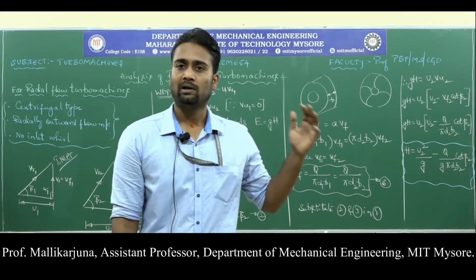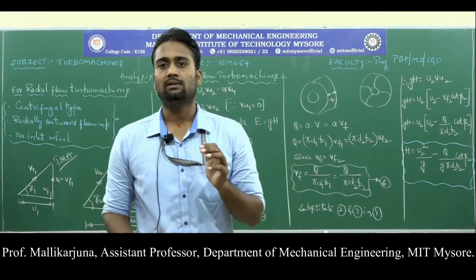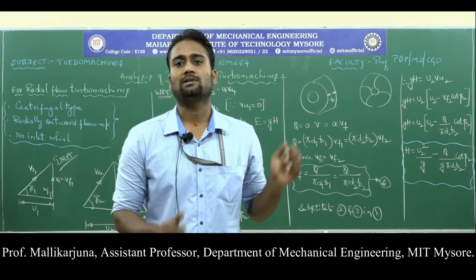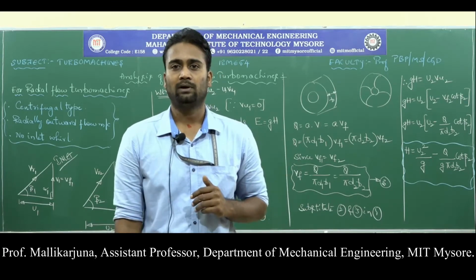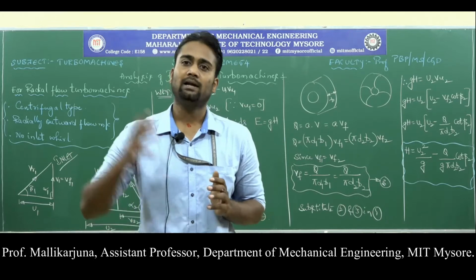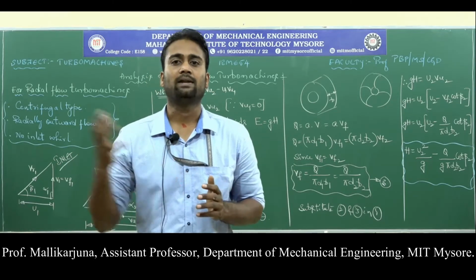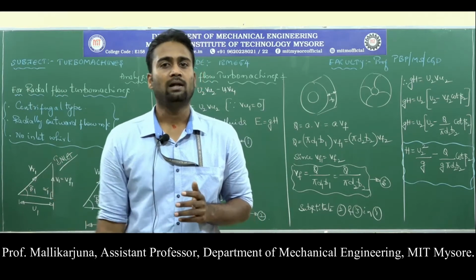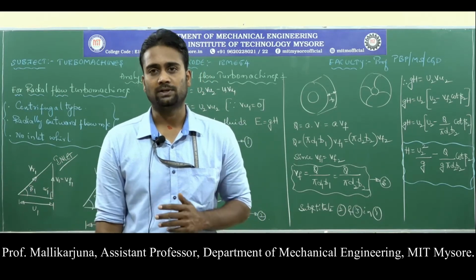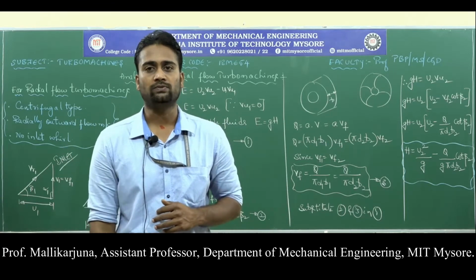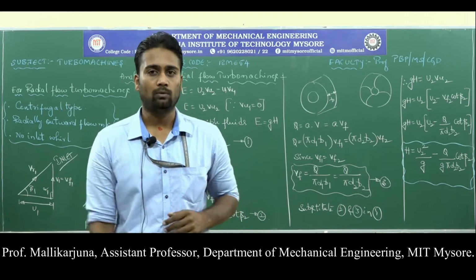In the sense, while entering into the machine, the fluid will be having no energy with it. It has to be entering at minimum velocity, and while exiting the machine has to impart the energy to it, and hence it will be at higher energy or higher velocities. That is why outlet part plays a very important role in case of power absorbing turbomachines.